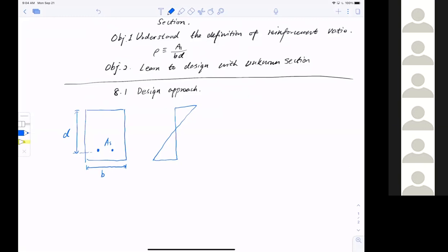Wade, Mr. Compton, are you there? Yes. Okay, great, sir. So let's see, we have a compressive strain in concrete, right? So what is the concrete compressive strain at failure? What is the critical strain epsilon cu right here? 0.003. Okay, thanks. So concrete compressive failure is 0.003, right? That's what we all know, okay?